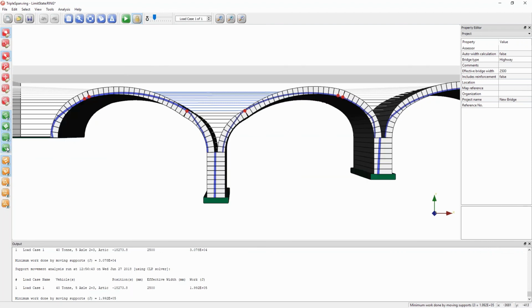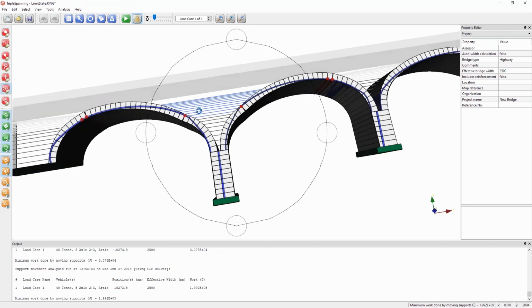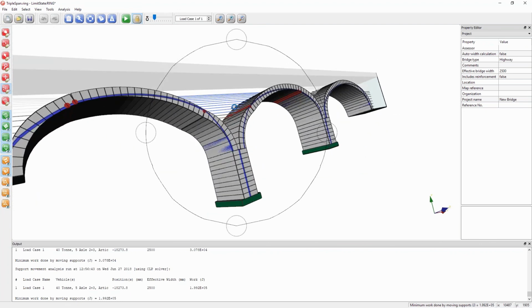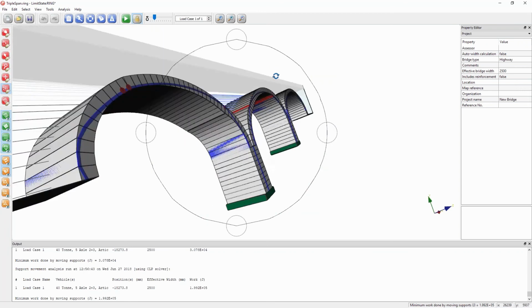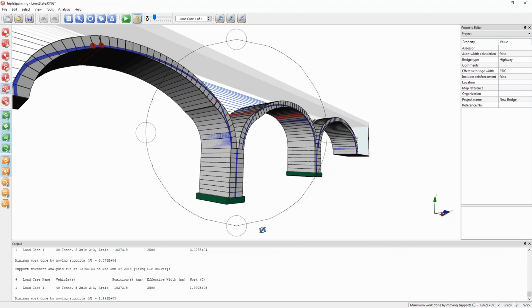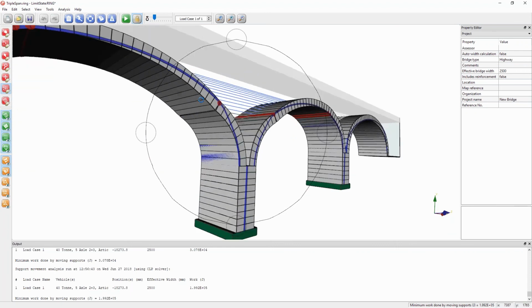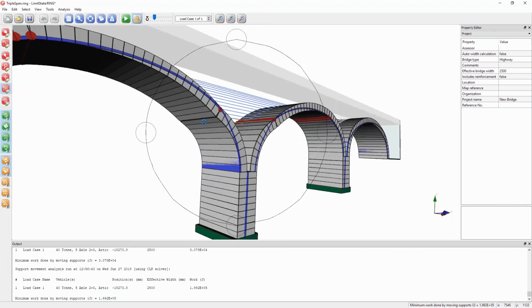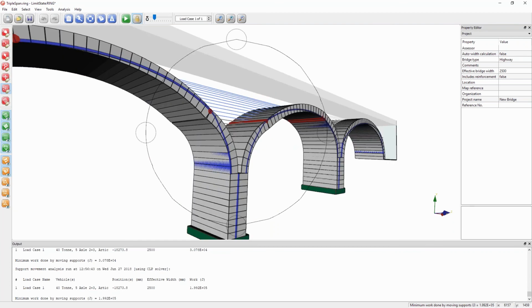And if we wanted to, we could look at that in a different way. We could say, okay, if I was looking at a bridge, I would be expecting a crack in, for example, the intrados like that. I'm not going to see the extrados crack.